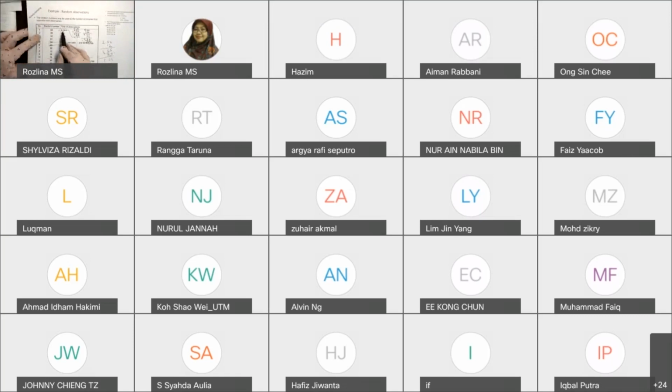So that means at 9:34 you use the element just now, whether busy or idle, there are many activities, activity A or B and so on. So when you go, let's say this is for a worker. At 9:34 you go to the production line, you see that worker is doing activity A. At 9:50 you go to that worker, now he is doing activity B. Now he goes back to activity A, until 10 observations. So you know how many percent he is doing activity A, how many percent maybe idle time. You get the percentage.